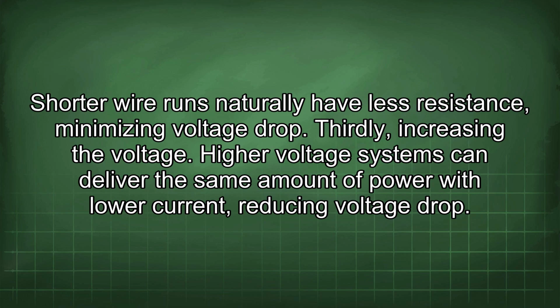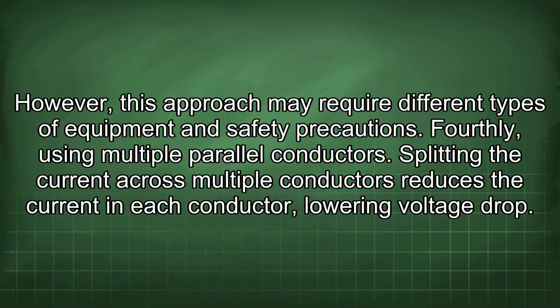Thirdly, increasing the voltage. Higher voltage systems can deliver the same amount of power with lower current, reducing voltage drop. However, this approach may require different types of equipment and safety precautions. Fourthly, using multiple parallel conductors.